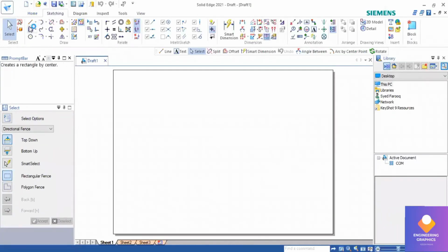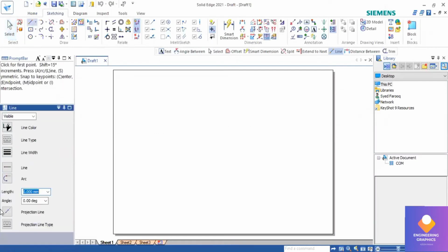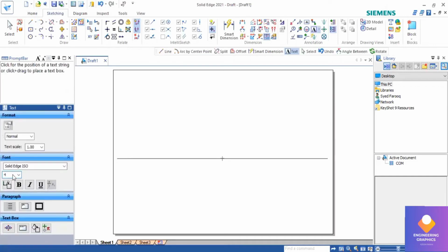line. First I'll be drawing XY line here. So XY line thickness I'll be considering 0.13. As I mentioned, you can consider 0.25 also, no problem. You can mention X, Y, VP and HP because we are considering a first quadrant. So mentioning of the X, Y and VP, HP is important because you need to mention in which quadrant you are doing it. Okay, we are doing in the first quadrant.